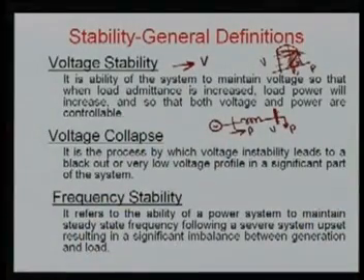Now, the frequency stability. As I said, there are three terms: delta, voltage and frequency. The delta is related to your angle stability, the voltage is related to your voltage stability, and the frequency is related to your frequency stability. No doubt the delta and the frequency are directly related to the real power, however the voltage is related to your reactive power. So, when we are observing the delta of the machines, it is basically angular stability. When delta and everything is in a normal state, but the frequency is changing severely, then it is your frequency stability.